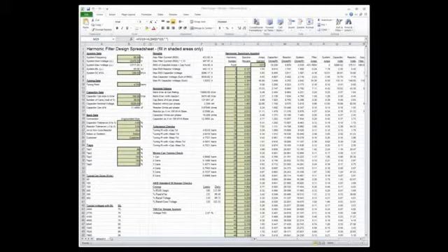And that is the reason why we typically apply fairly large size single tune banks for that reason, because when you're doing a lot of switching of banks, you got all the additional reactor costs, you're going to have all the vacuum bottle costs for switching. And the other reason is, believe it or not, but if you apply a 5th harmonic filter, it will absorb 7th. It will absorb 11th. So it's not just filtering only 5th out of the system.